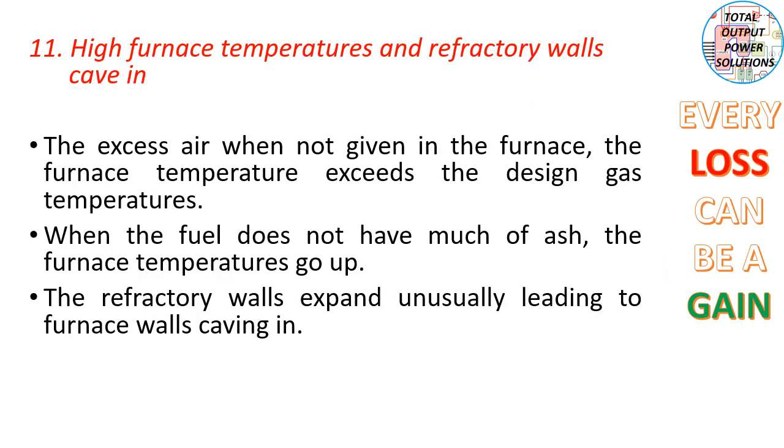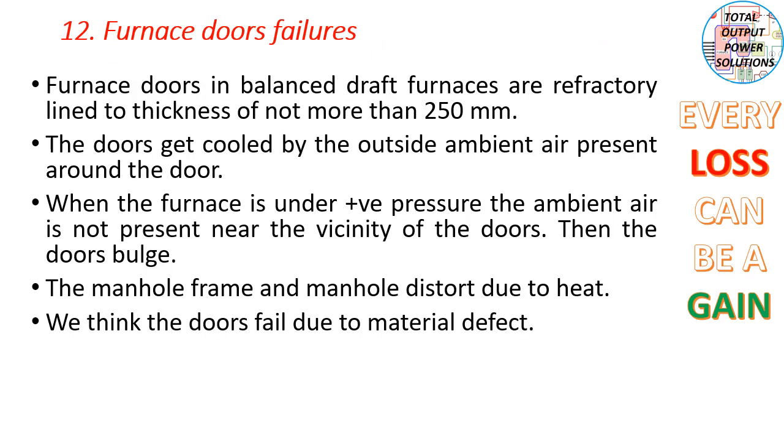High furnace temperatures and refractory walls caving in. When excess air is not given in the furnace, the temperature exceeds the design gas temperatures. When the fuel does not have much ash, the furnace temperatures go up. The refractory walls expand unusually, leading to furnace walls caving in.